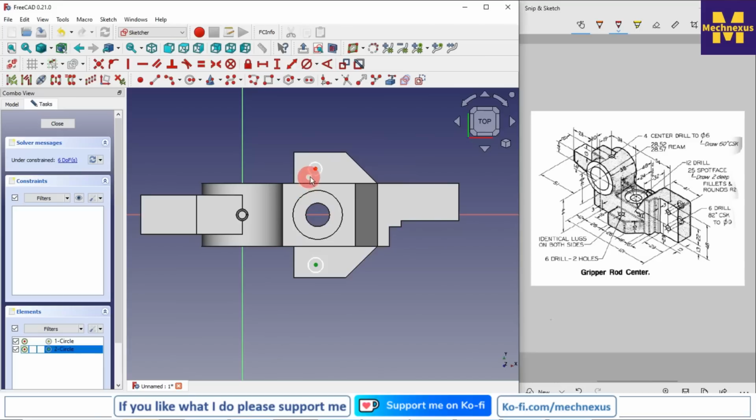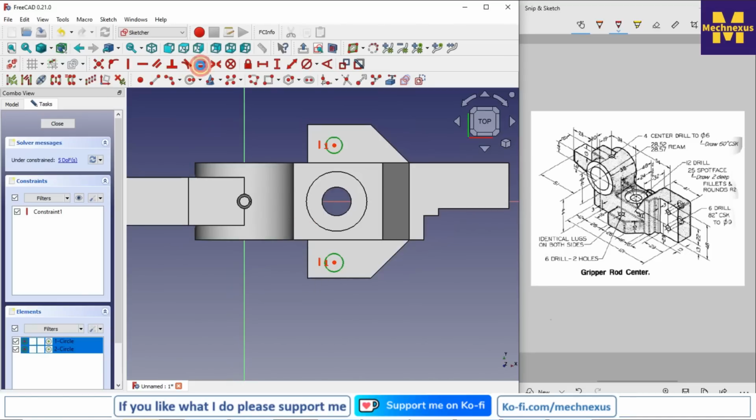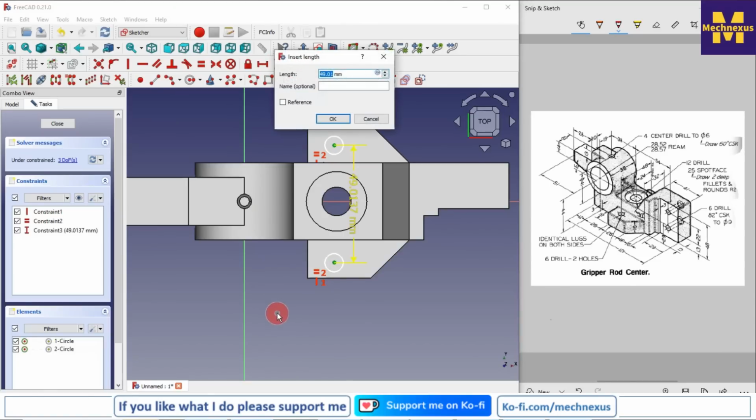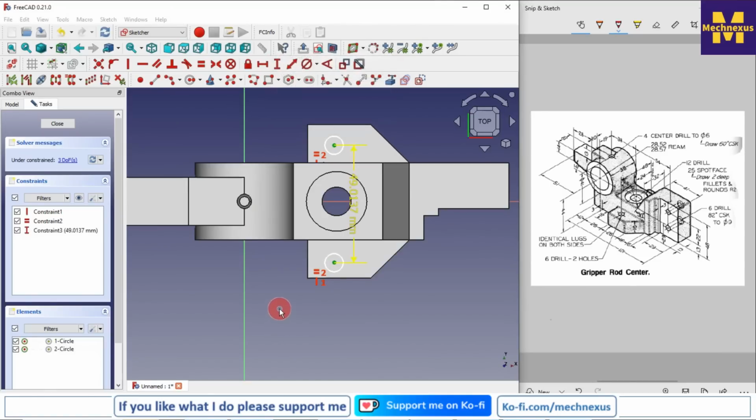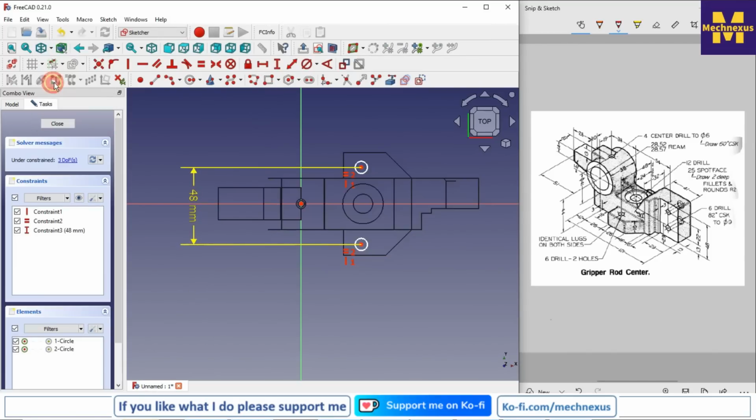First we add the vertical relation with these 2 holes. It is a 6 mm drill, so both are the equal, so I will give the equal constraint. And now we will give the dimension which is of 48 from this hole to this hole, so I will select this 2 center point and add the vertical dimension of 48, and I will switch to the wireframe.